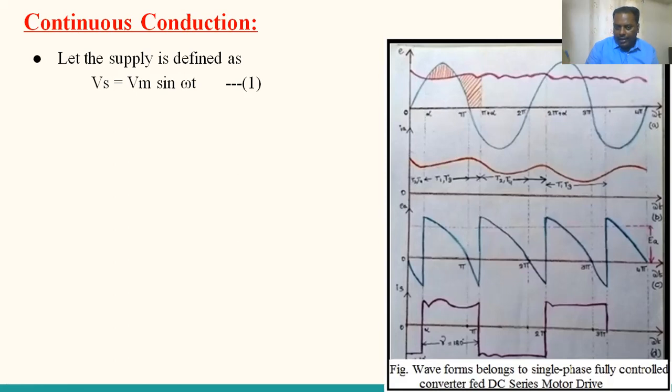The supply voltage is reversed. This tends to change the direction of the back EMF as well as the speed, so that the machine acts as a generator and produces electrical energy. This produced electrical energy is fed back to the source. Here the switches are allowing reverse conduction, reverse braking, so that power is transferred from the load to the source. That is the reason the average output voltage continues on the negative side.